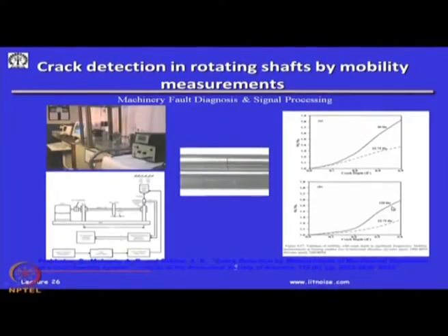And this is a good indication that by monitoring the mobility of a system, I can tell that the system has undergone a crack. Just by monitoring vibration, I would not be able to tell whether a shaft crack has occurred. And this is actually published in one of our journal papers. So, to summarize, for various crack depths the mobility is very sensitive, and these are at the rotational speeds 22.75, 40 hertz, 22.75 at 120 hertz, and so on. At different speeds we have seen the mobility.